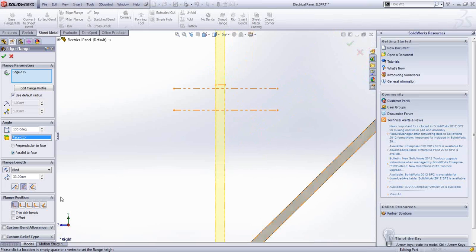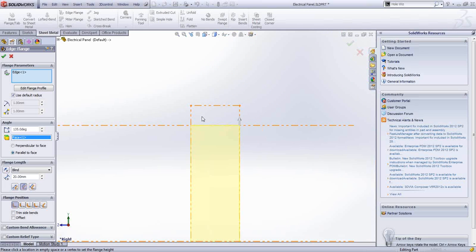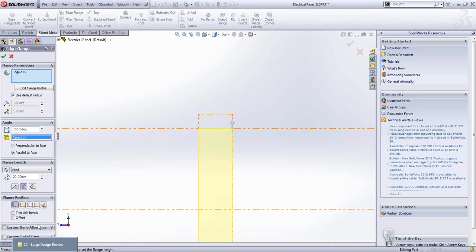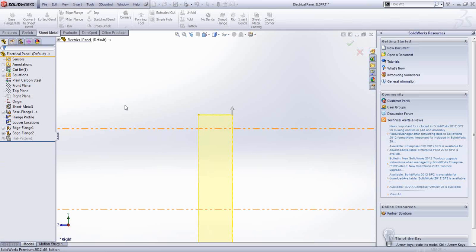And to get this length right, it used to be a struggle previously. Like I wanted 20 mm length. I want it right till here. So now in SolidWorks, I can choose this tangent bend option, so it will align properly. Let me close up the corners.